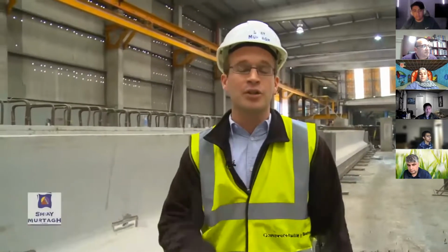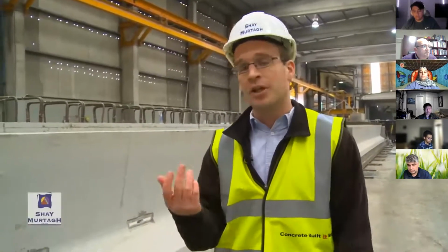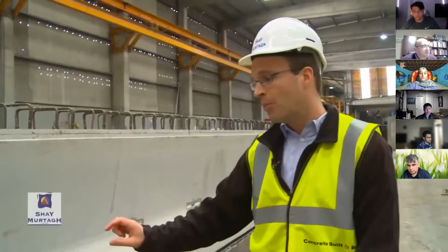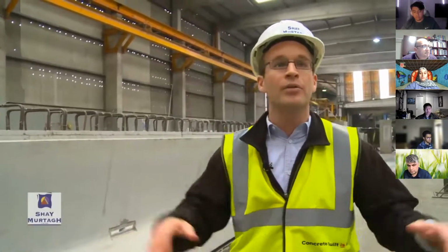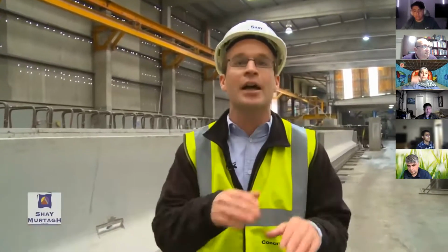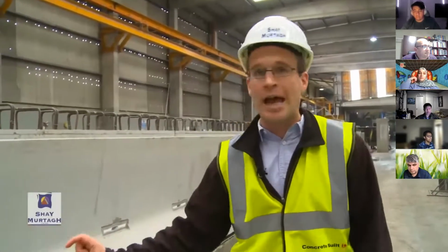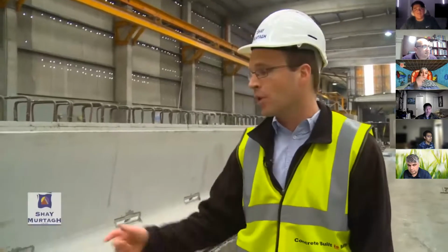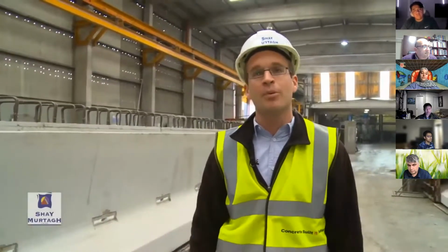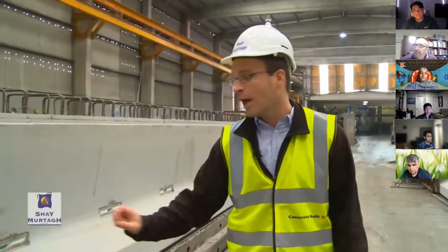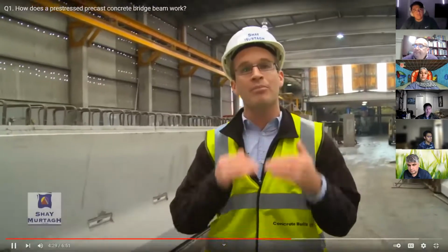Now, this is beneficial with regard to deflection checks as well. Generally for bridge beam design, we don't need to carry out rigorous deflection checks, but from an aesthetic point of view, you don't want a beam visually sagging on site. So this natural camber that results from the pre-stressing operation itself will help eliminate the potential that that beam would be visibly sagging on site as well.